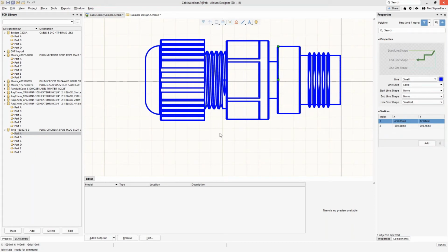So how do we draw something like this without spending days or trying to make it look very realistic like this? Well, you can take advantage of the fact that any step file that you have can be brought into a mechanical tool, converted into DXF, DWG format, right? You can take advantage of that. So as long as you have the step of it, you can convert it to DXF, DWG, and you can get something that looks like this. Now, because I'm a little pressed for time, I didn't want to go through that whole process of opening up SolidWorks and converting it, but it's pretty easy to get the DXF DWG. What I will do is show you how to import it in.